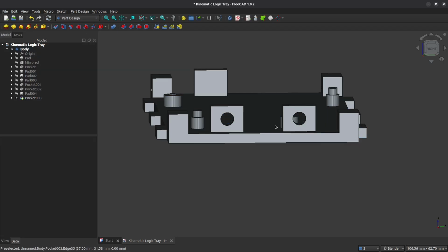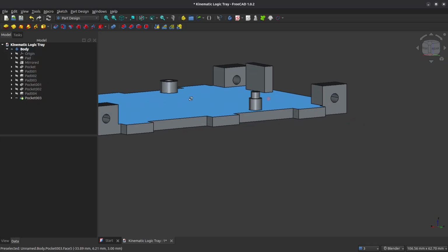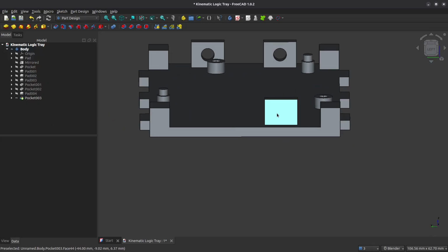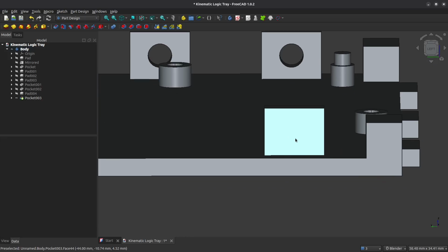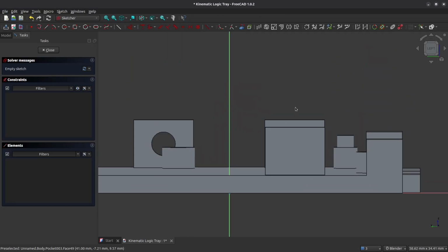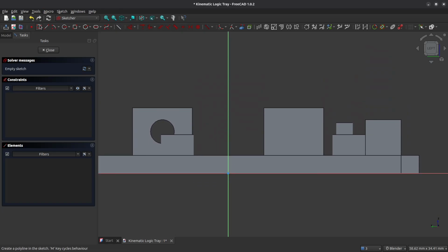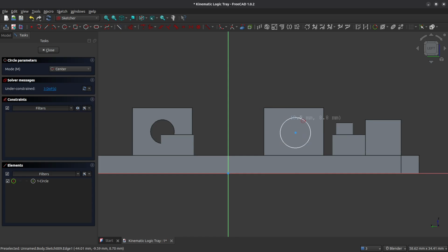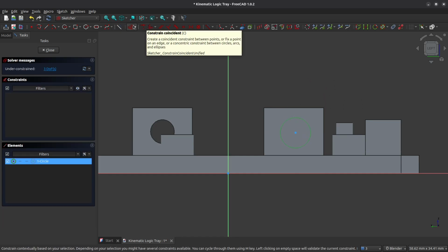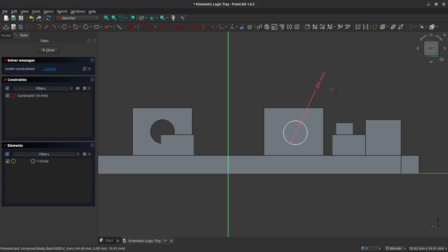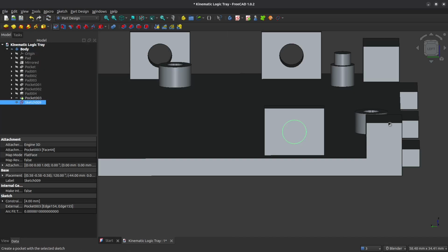They're 3 millimeters thick, so our 5 millimeter default clears it. We're going to rotate around and do the singular tab on the other side in front of the Arduino. So grab our circle tool, again, set its diameter to 4 millimeters, reference the left and right edges, and make it constrained in the center of that tab. Our constrain symmetric tool. All right, and so we can pocket that now.